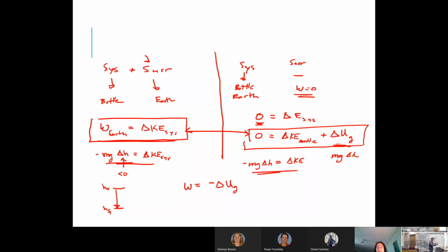So you do external work by pushing the cylinder, you increase the pressure, and the system responds by heating up. Momentarily, right? If you do it really fast, you can start a fire. Yeah, fire piston? It's literally that. You just increase the pressure so fast that you go above the flash point of cotton and it catches on fire.